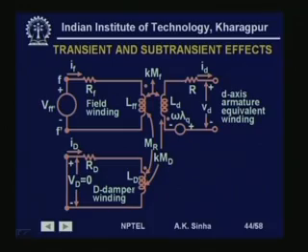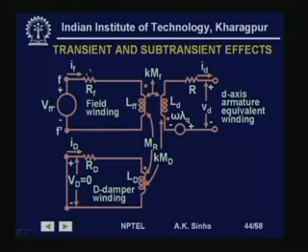There is no current flowing through this, and these two circuits are only valid, and then the field time constant is somewhat larger. So, that again dies out with some time, and then finally we have only the synchronous impedance of the circuit remaining, and therefore we define 3 different reactances or impedances for this circuit.